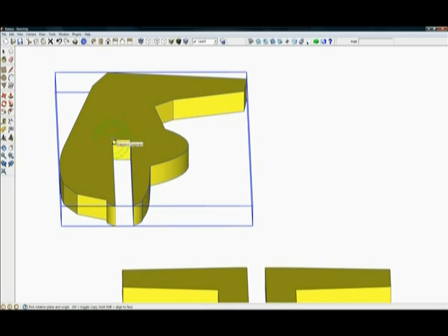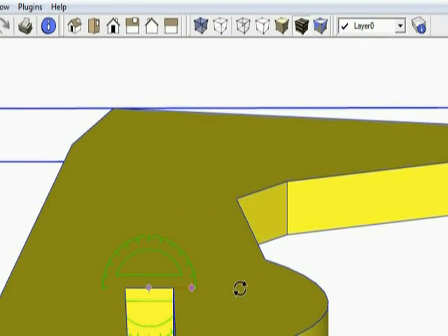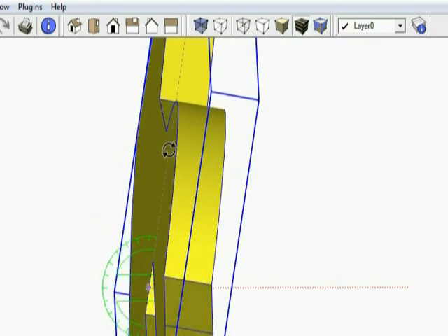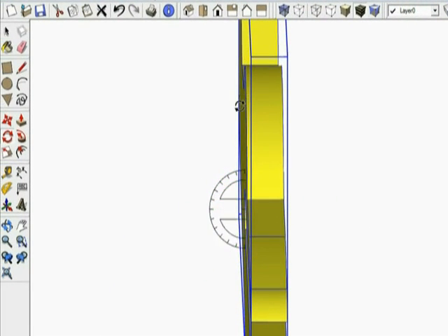So if we do it here, where we know that this is already 90 degrees to the green line that I showed you earlier, then we know that this is a great place to rotate. So we want our green, we'll select it, we'll pull out a line, we'll go this way with it, and it'll lock to 90 degrees. We'll select again, and now we've got that piece.